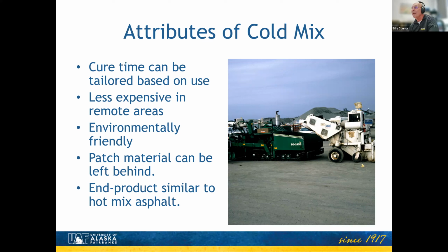And we can also leave some patch material behind. Sometimes what we do is bring in a tote of, say, the cutback material, mix it up, put it in plastic bags, and leave it in the community for patching material. And when all is said and done, if it's done exactly as it should be done, it's pretty much the same as hot mix.